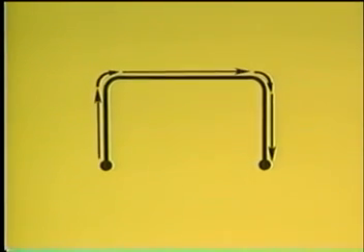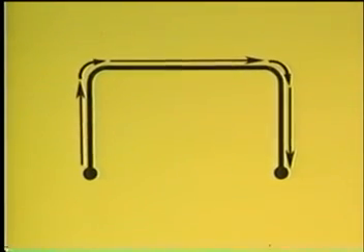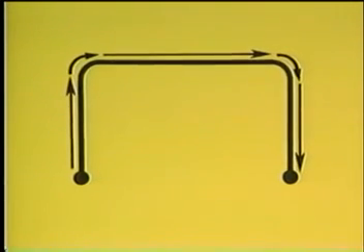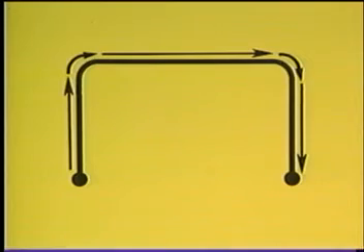Now, let's review what you've learned in this program. Continuity is the existence of an uninterrupted current path of low resistance between 2 points. Continuity tests are used to locate broken or burned out connections, common connections or shorts, and to check the bias of diodes.